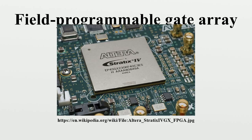Examples of such hybrid technologies can be found in the Xilinx Zynq-7000 all-programmable SoC, which includes a 1.0 GHz dual-core ARM Cortex-A9 MPCore processor embedded within the FPGA's logic fabric, or in the Altera Arria V FPGA, which includes an 800 MHz dual-core ARM Cortex-A9 MPCore. The Atmel FPSLIC is another such device, which uses an AVR processor in combination with Atmel's programmable logic architecture.